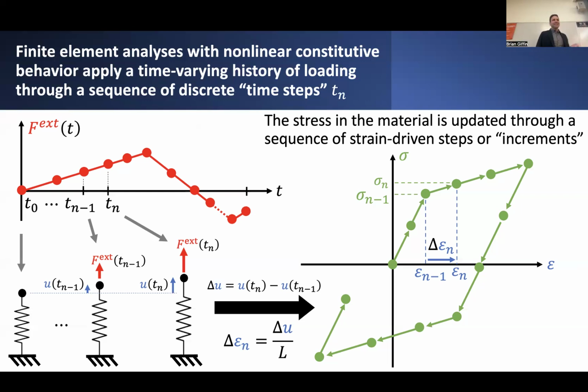So ultimately, when we're considering any kind of nonlinear material behavior, we want to assign not just the total load that we're putting on the structure, but the full history of loading, so that we can better understand what's happening at the material level. That's really the key distinction I want to point out, which is common to a lot of nonlinear material models and behaviors: they depend not just on the current state of strain in the material. They often depend on the entire history of strain, or history of loading, that the material has experienced. So that's a critical distinction.